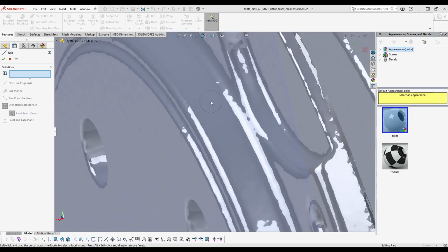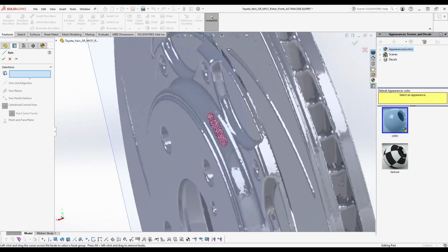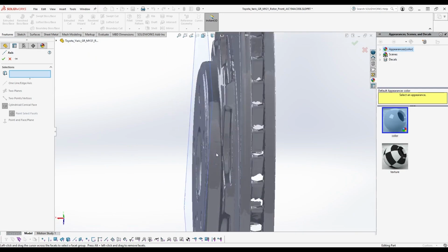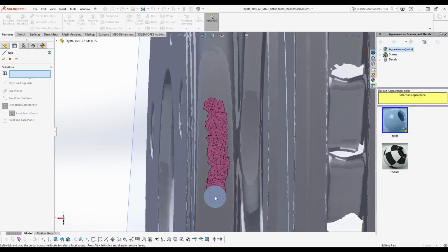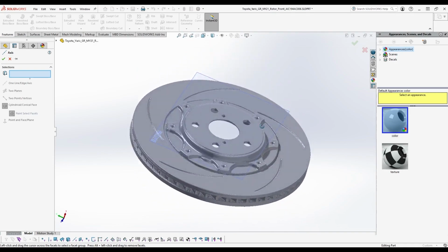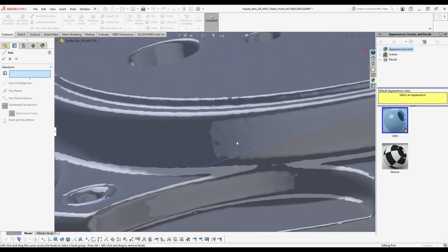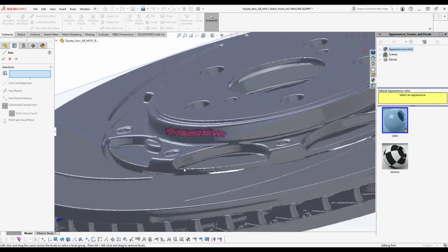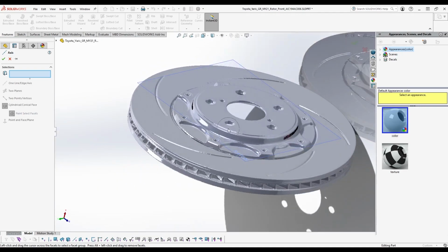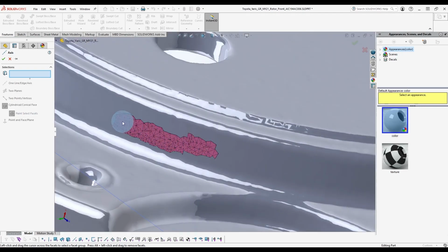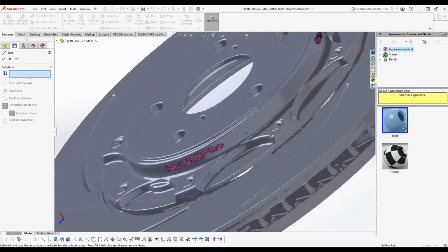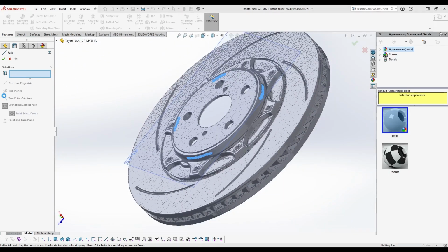And then it allows you to come in and paint a few of these faces. So this is a CNC machine edge that will be done in the same operation as that front face. So they should be as perpendicular as it gets. But what I'm doing here is just painting a few spots. Obviously, if I really want to be super accurate, I might go a bit more than that, but that's probably going to do the job.